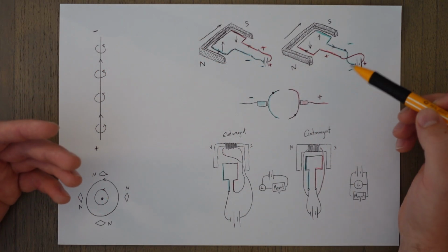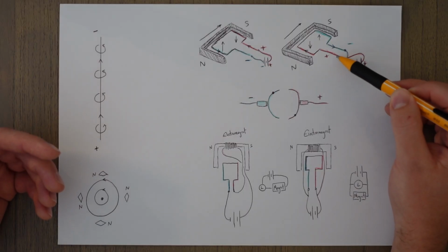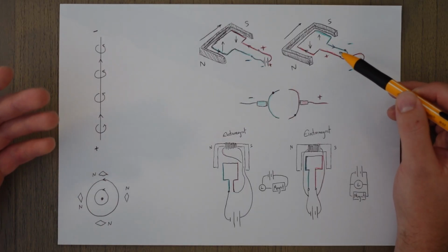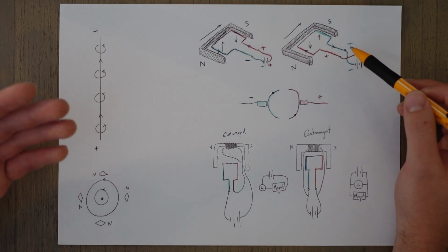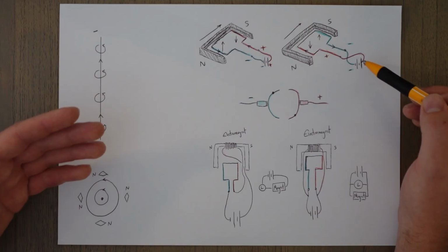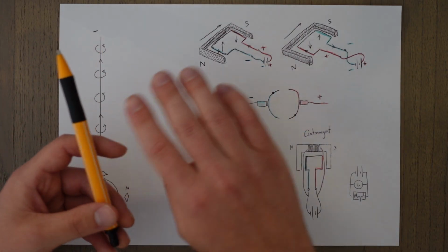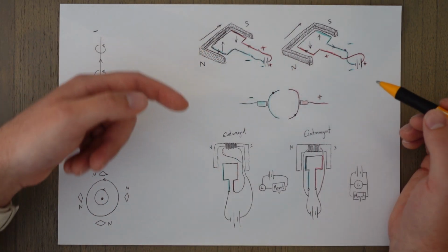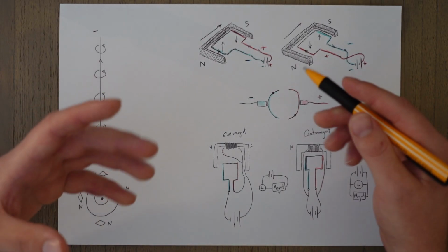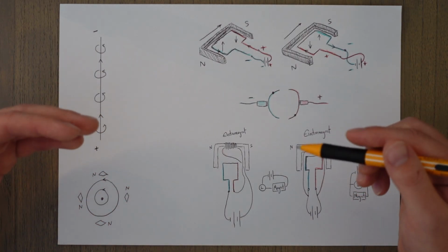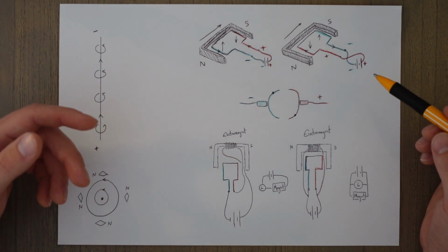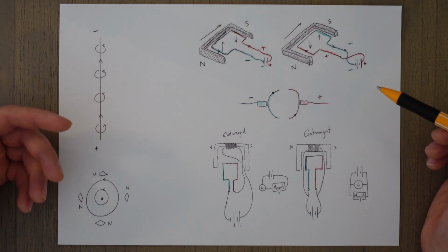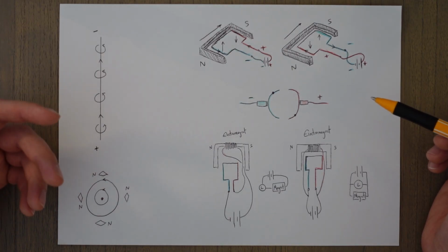We therefore need to change which leg of the loop is connected to the positive side of the battery and which is connected to the negative side, to ensure a constant direction of current through each section of the loop that is influenced by the field. The key is to do this swap at the correct time through a device called a commutator, and create a seamless rotation of the loop of wire.